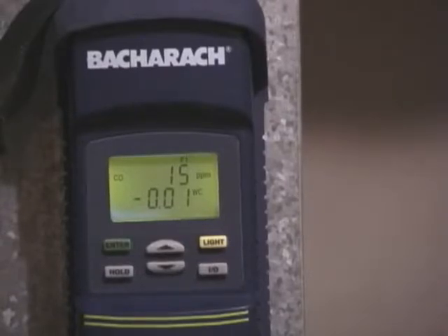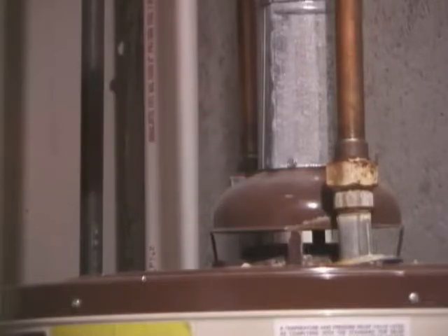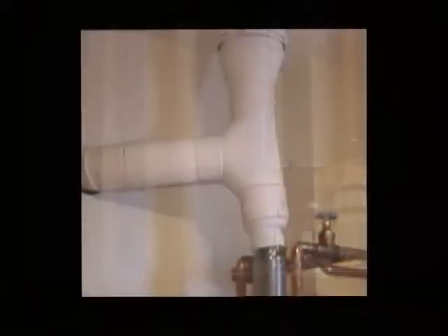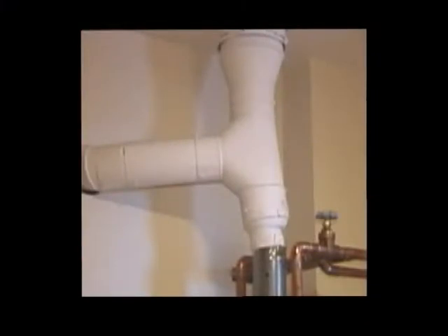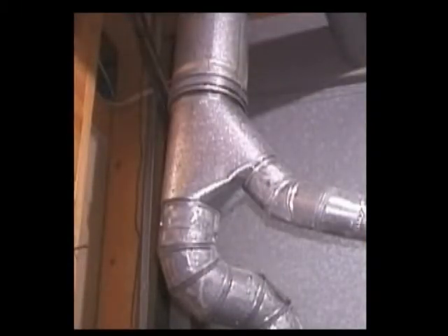And after 2 minutes or so, we see that the pressure in the vent connectors of both the furnace and the water heater are now negative 0.01 inches of water column. And the smoke now enters around the draft hood of the water heater as it should. This phenomenon seems to occur quite regularly under this type of setup, regardless of whether the water heater is connected to the common vent with either a T or a Y connector.